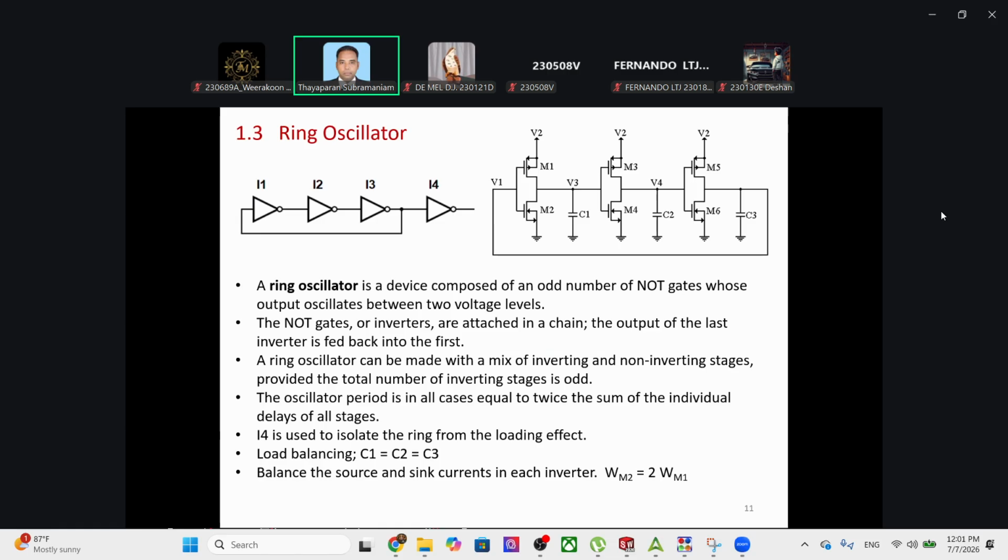The low quality design becomes 2%, 5%, 10%. That becomes a serious issue in digital design. If you take some digital subjects later, probably I will discuss what kind of issues we will have there. But at this time, it is important to design low jitter clock modules. So in order to have low jitter clock modules, it is important to match the load as well as match the gates. Similar gates we have to use.